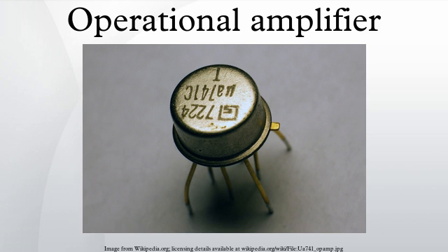This dynamic response coupled with the very high DC gain of the op-amp gives it the characteristics of a first-order low-pass filter with very high DC gain and low cutoff frequency given by the GBWP divided by the DC gain. The finite bandwidth of an op-amp can be the source of several problems, including stability. Associated with the bandwidth limitation is a phase difference between the input signal and the amplifier output that can lead to oscillation in some feedback circuits. For example, a sinusoidal output signal meant to interfere destructively with an input signal of the same frequency will interfere constructively if delayed by 180 degrees, forming positive feedback.